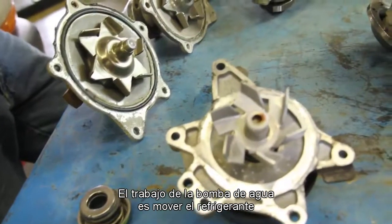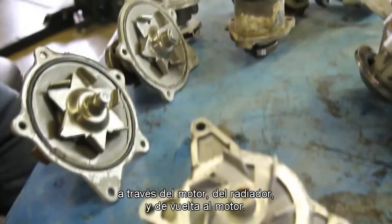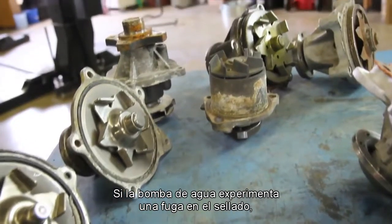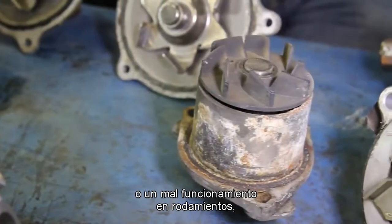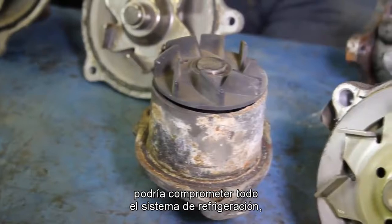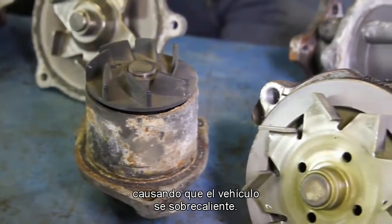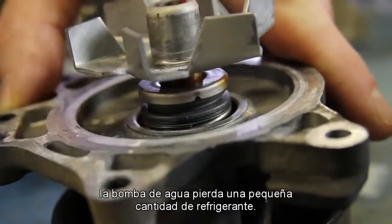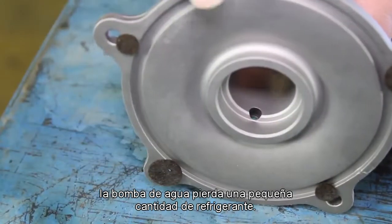The water pump's job is to move coolant through the engine to the radiator and back to the engine. If the water pump experiences a leak from the seal, a cracked housing, broken impeller, or a bearing malfunction, it can compromise the entire cooling system, causing the vehicle to overheat. It's not uncommon under normal operating conditions for the water pump to weep a small amount of coolant.